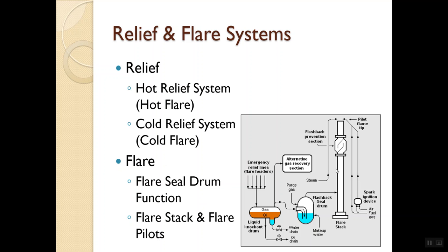We'll show you what the flare looks like in one of the labs. We'll show you how all the piping connects into all the exhaust piping from the plant. The tops of all the vessels and the columns exhaust all into one header pipe, and then it all goes into the flare system to safely burn off any hydrocarbons or any pollutants that we have.